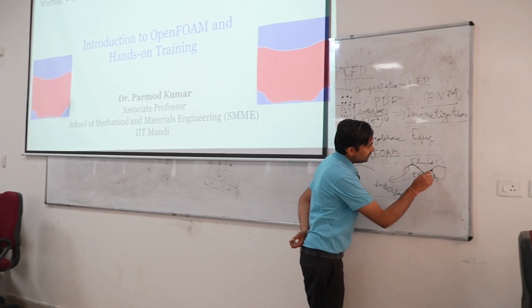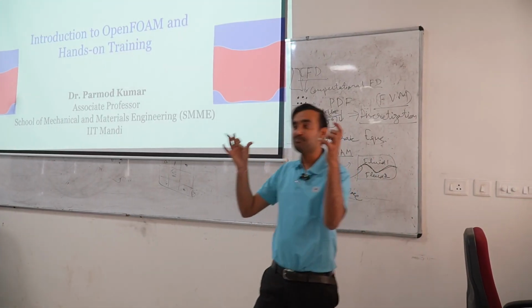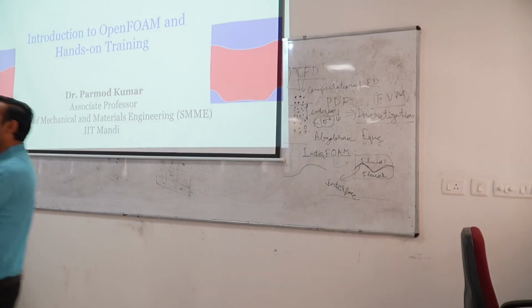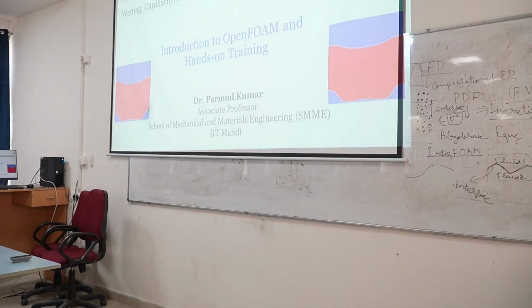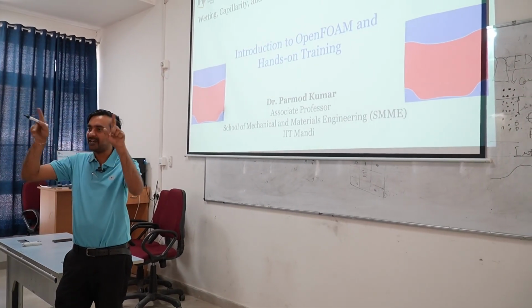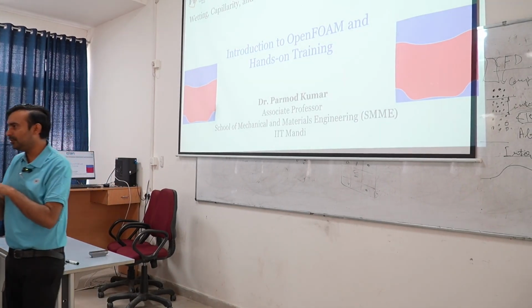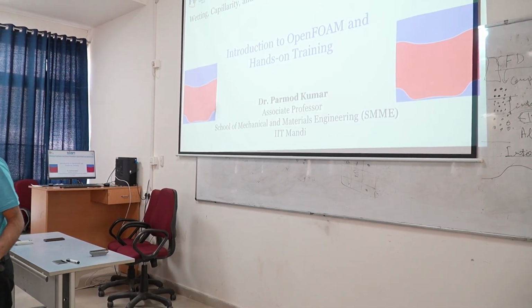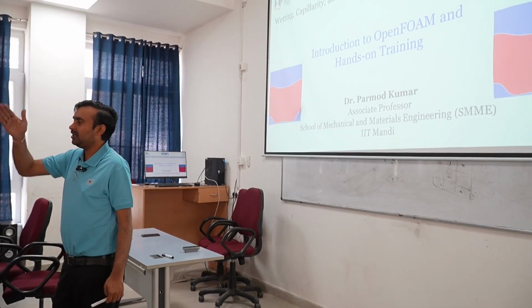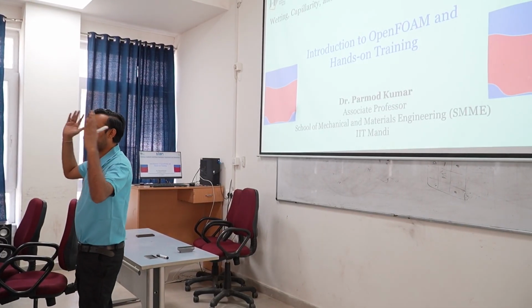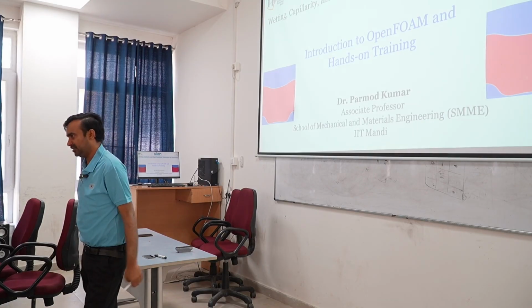So at this interface, I need to supply some boundary conditions which will be applicable at the interface. Typically in a single phase flow, if the entire pipe is filled with the same type of fluid, within the domain we need not define any type of boundary condition. We only define boundary conditions at the inlet, outlet and at the solid boundaries.